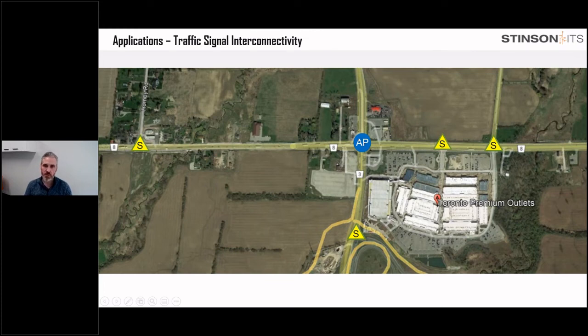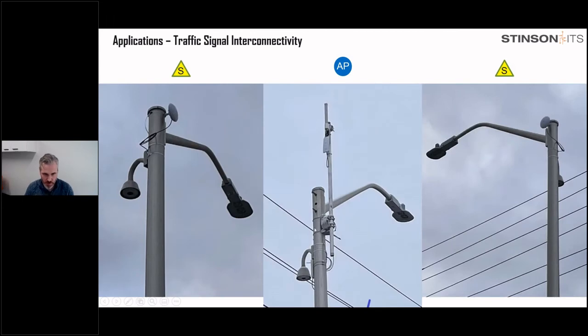So what we installed was an omnidirectional antenna at this access point on one of the traffic signal poles. And then we put one of those NanoBeam stations. So this is the master or the access point. There's the Rocket Prism with an omnidirectional antenna. And then each of the stations or subscriber radios had just a small NanoBeam pointing back at that location and connecting them all together.